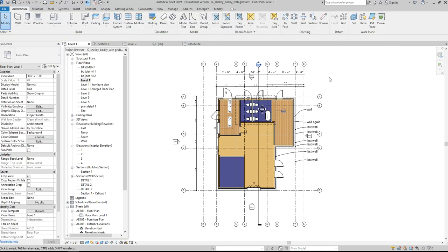Now, I'm going to create my foundation walls in my main level floor plan. I'm going to create them in the level above the level I want to view them in, all right? And the reason I'm going to do that is because foundation walls are a little bit different than regular walls in that when they are defined, they define from the top down instead of from the bottom up, okay? It's so confusing. And sometimes this is one of those things where I always forget the top and bottom constraint. I have to do it a couple times, you know, anyway.